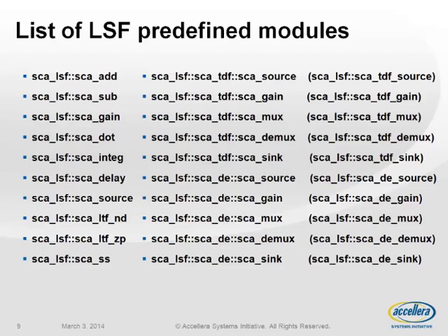And you can see on the second column that we can also have some interfaces between LSF and TDF with this kind of constructs and primitives that belong to LSF and TDF. Same thing for gain, mux, demux, sync. And same thing also for the discrete event. So LSF models can be integrated both in a TDF and in discrete event.